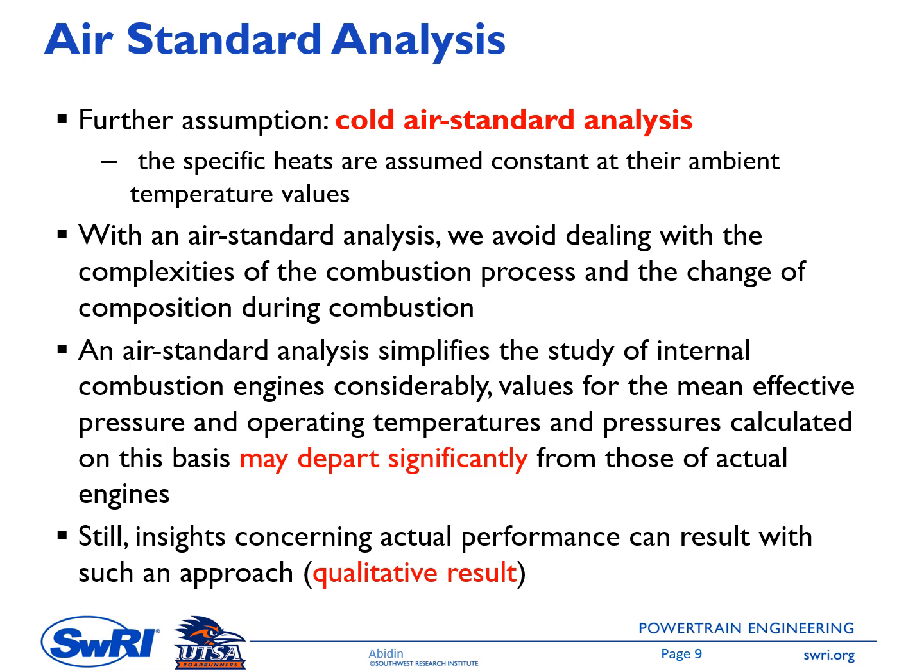So you can still use this approach for a qualitative analysis, but not a quantitative analysis. You can still see the trend, for example what the engine efficiency will be if we increase the compression ratio. With this simplified analysis, you can still get the correct trend, but the absolute number might be wrong.